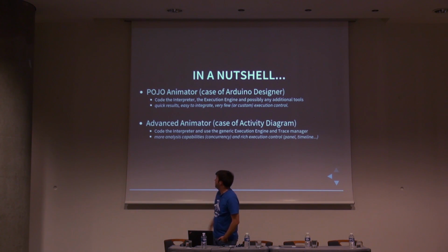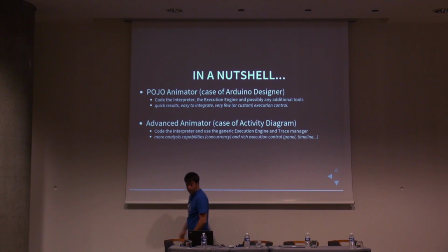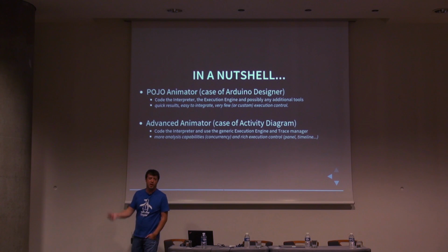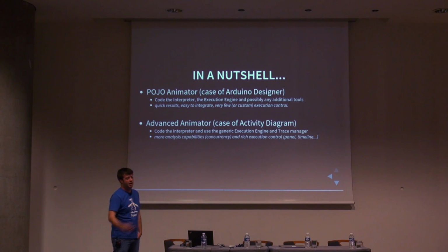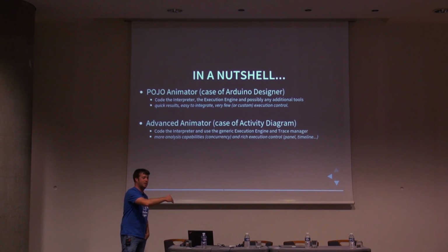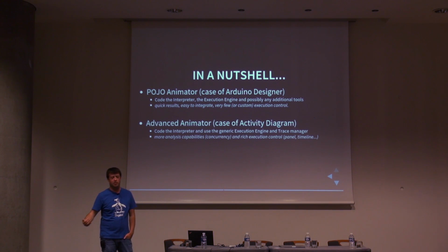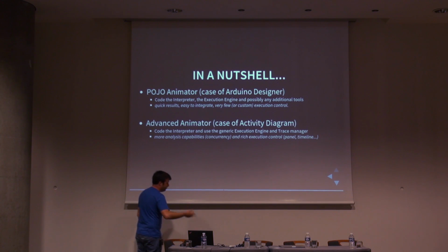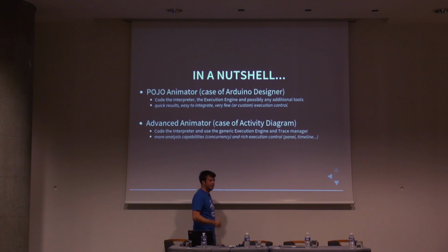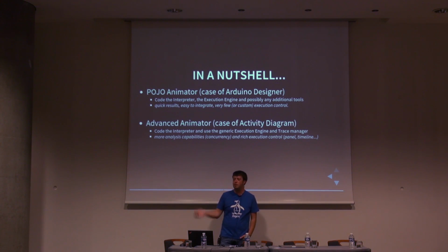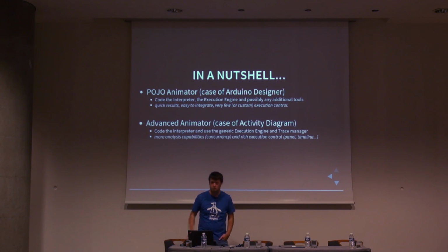And in this case, it gives you more capabilities, like checking concurrency aspects, and more importantly, going back in the trace and maybe making some decision at some point and trying what if my push button is not pressed at this point, what happens next? So you can easily go back in history and go forward and get back again to the first state you were.